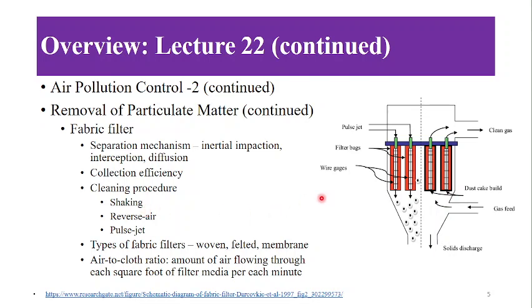In reverse air, from where the air is coming out, from there you input the clean air, so that these particles which are in the pores may get removed. And the next is the pulse jet. For a short duration of time, you send a pulse of high velocity air, and because of this high velocity of air and this short duration,